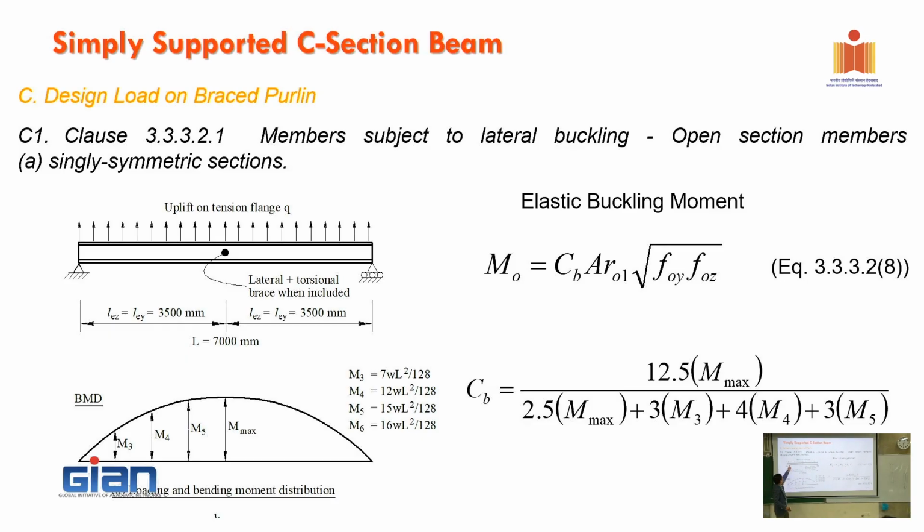And when the length between the segments reduces a lot, that will increase a lot, and the buckling load will be through the roof. It's elastic buckling, but it's not a problem. The problem now, if you put a lot of restraint in here, is it goes to section capacity. The section now is going to yield, or if it's thin, it's going to buckle in